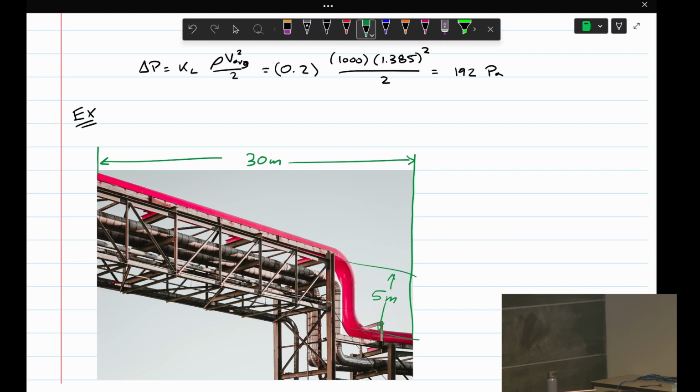It sort of implicitly depends on that, because if you pressurize the system a lot, you have a higher flow rate, and then you'll have a lot of pressure loss. But for the same flow rate, it doesn't depend on the pressure at all. Remember, pressure is kind of a measure of potential energy, so this is just a loss of potential energy.